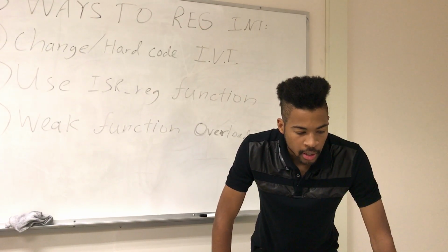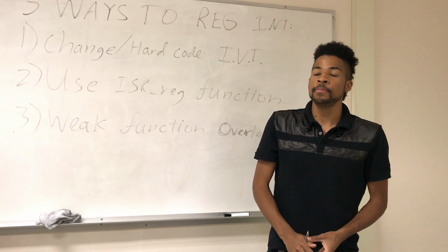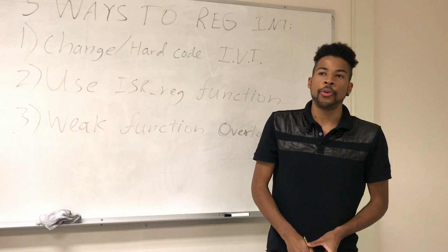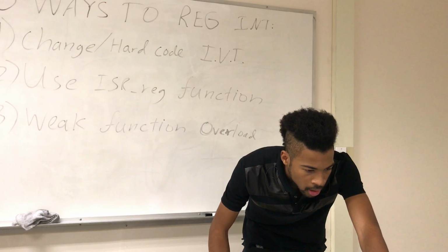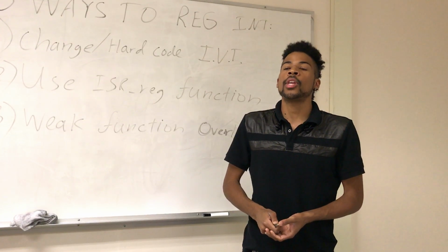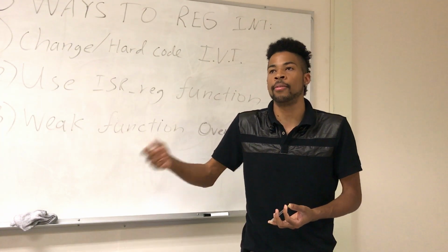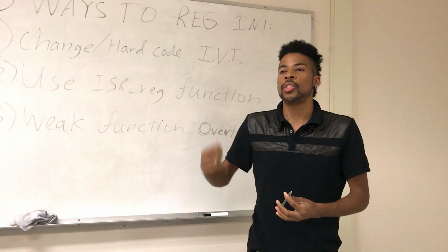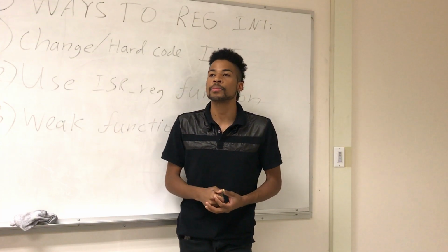I would actually suggest, and it states inside of the lab, that you cannot use printf inside of a service routine. If you want to use printf, you can use the debug printf. But the best thing for you would be not to use printf, but to have either a global variable, which can be thread unsafe, or to use a vTask trigger, or a semaphore take or give from ISR. So use the FreeRTOS APIs to send triggers to other tasks to do something when something occurs.